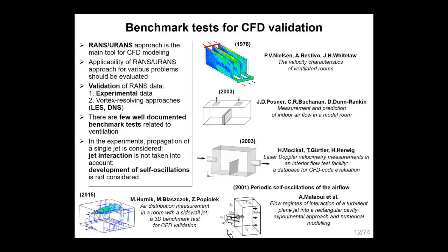However, if we still have some empiricism in large eddy simulation modeling, large eddy simulation also requires validation. Unfortunately, there are very few well-documented benchmark tests related to ventilation, and in the experiments available in the literature, propagation of a single jet is mostly considered. Jet interaction is not taken into account, and development of self-oscillation is not considered, except in this test by Matsui et al. So here are just several tests that were used in our research group for validation of CFD modeling.